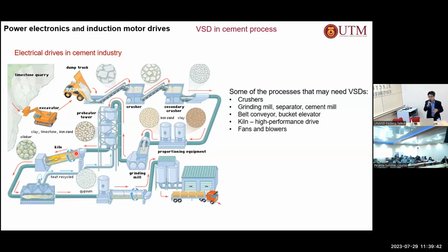But nowadays, I think most of the cement industry, including PT Semen, I was told by Dr. Imran, uses direct torque control in the kiln drive, all right, which gives you precise torque and speed control. It reduces the stress on the mechanical parts, reduces the starting voltage, starting current, starting speed, and so on. And it's not easy to control, but it is implementable by using the ACS 2000 drive systems from ABB, which uses direct torque control.